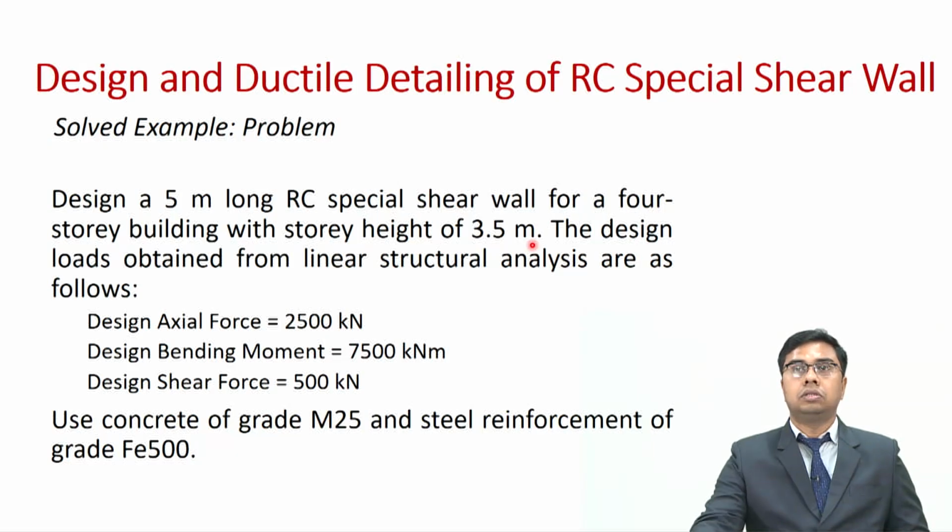The design loads obtained from linear structural analysis are as follows. This is usually obtained using commercial software. So, in this case, we have obtained the design axial force to be 2500 kilonewton, the design bending moment as 7500 kilonewton meter and design shear force as 500 kilonewton.